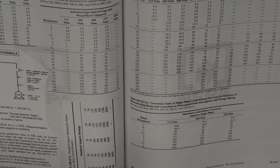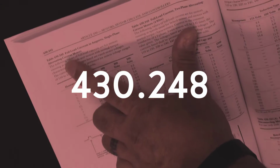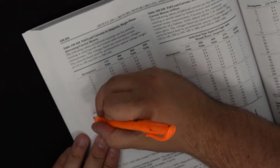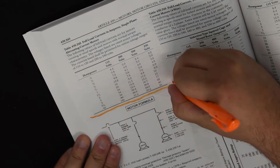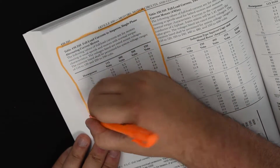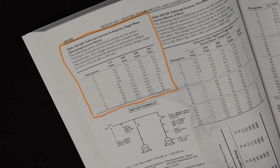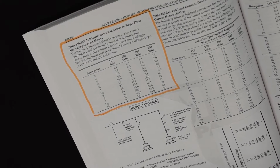Now the next section we're going to go to, before we get into actually doing any math, is 430.248. And this is our motor section. 430.248 is full load currents in amps for single phase alternating current motors. So we're going to box this table in, make it jump off the page as well. When we're dealing with a motor, we're going to come back here to find the ampacity of that particular motor.